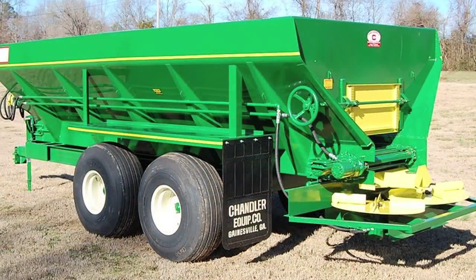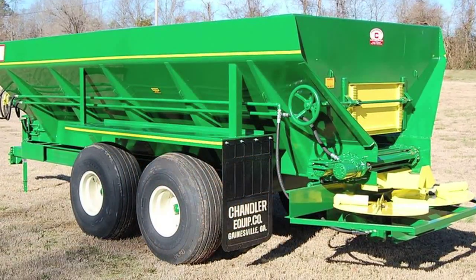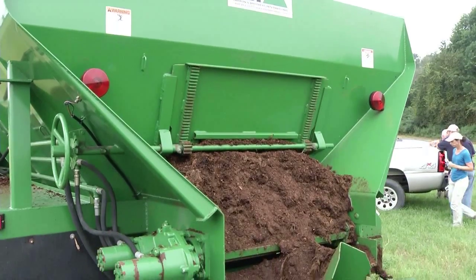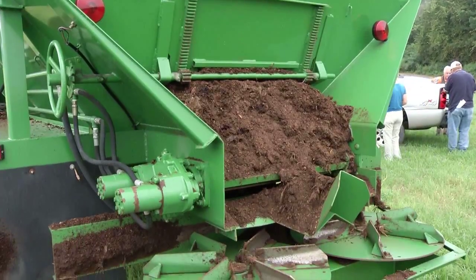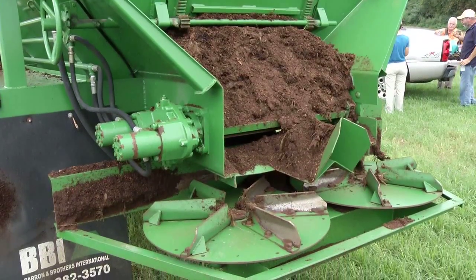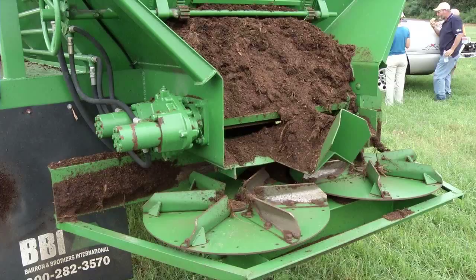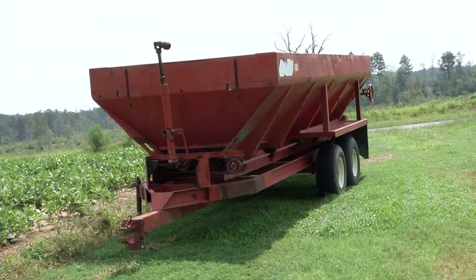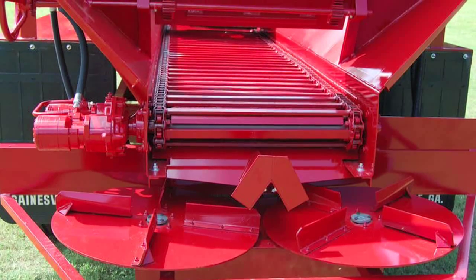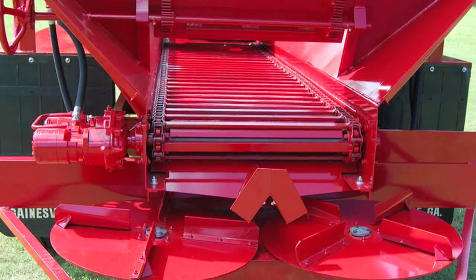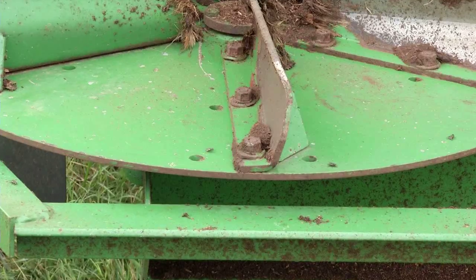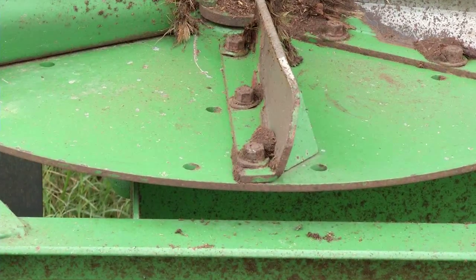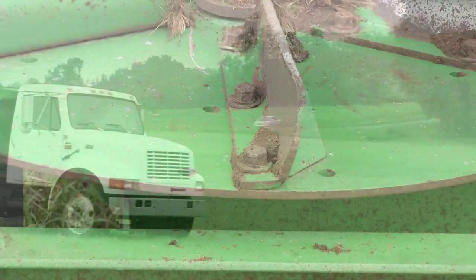The double disc spinner spreader like this one can apply litter at a much faster rate than the box spreader and is hence more popular. Therefore, we will focus on spreaders with double spinners. Spinner spreaders are either truck-mounted units or trailer units pulled by a tractor. The conveyor at the bottom of the hopper delivers litter to the paired spinning discs. Vanes on top of the spinner discs throw the litter behind and to the side with a typical swath width of 30 to 50 feet.